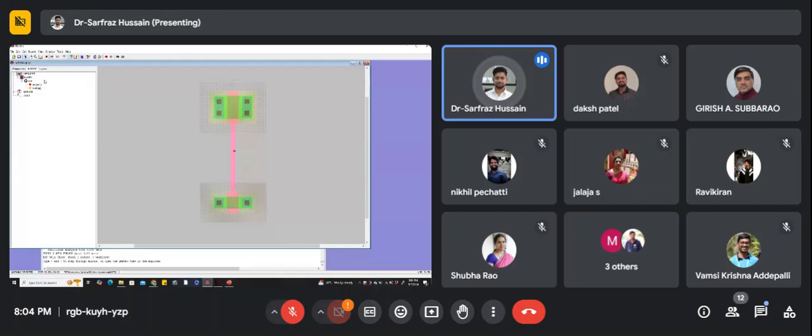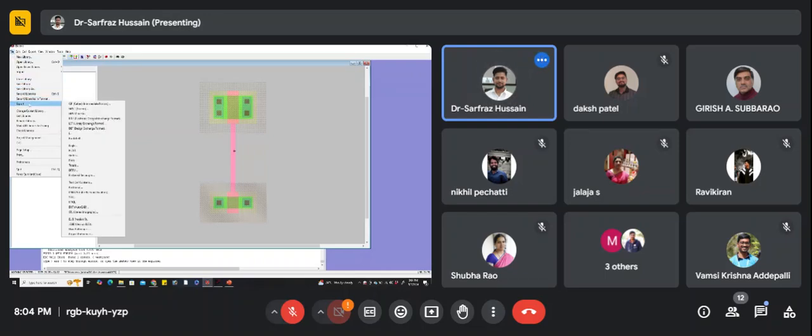And here also you can see after doing the layout and let's say we are creating the pad and all. So input output pads, everything if we create it, then we can go to the file and here you can see there are a lot of options. So you can export the design into a GDS2 stream. So here this is very, very important. There is another important one, that is the CIF is also there. But for example, whatever we need to do, here GDS2 is very, very important. So after you create this particular layout, once you put the pad frames, when you put the input output pads, then you can go for this GDS2 stream generation.